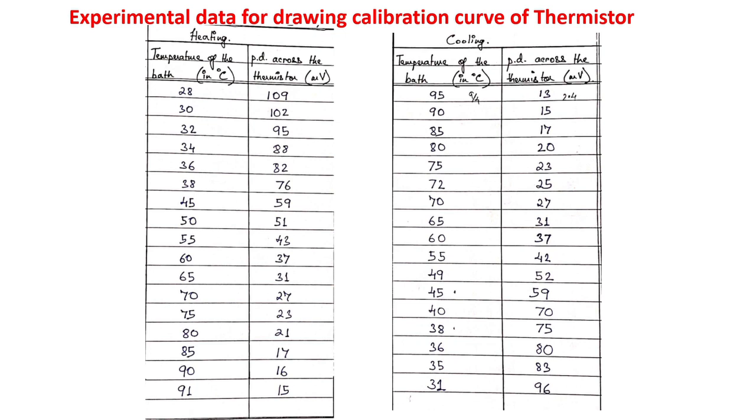It will supply the corresponding EMF in the circuitry, which will be checked by the circuitry, and accordingly the temperature of the water bath will be controlled at the fixed point by running the heater or by disconnecting the heater within the system.